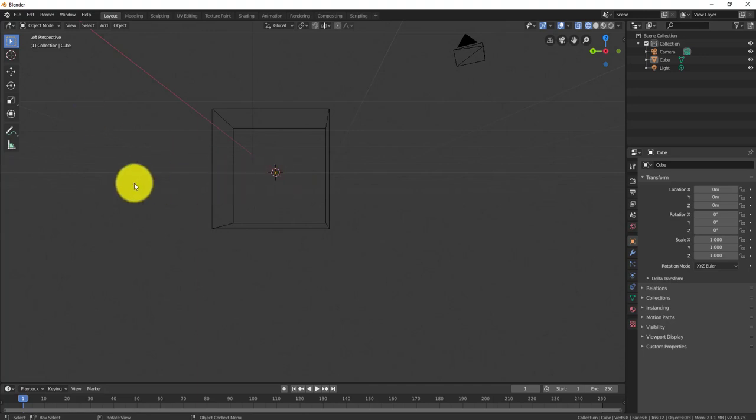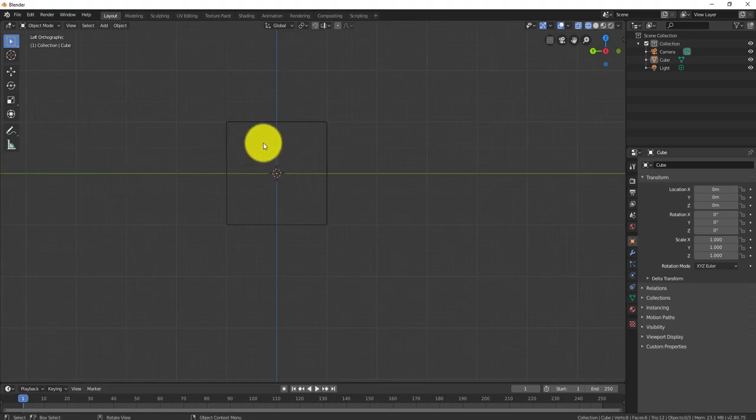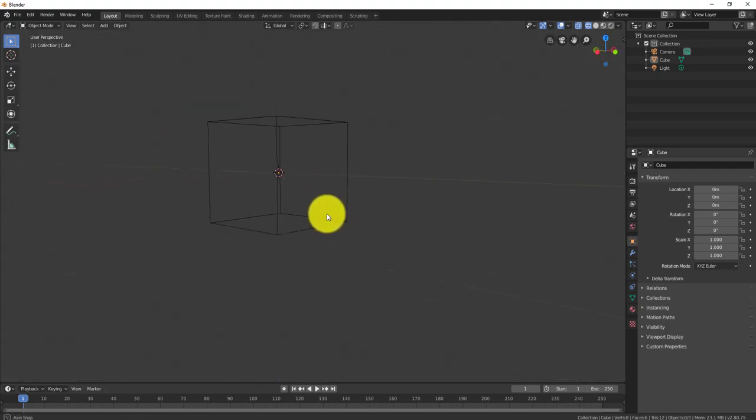If I press 5 again, it shouldn't surprise you that I'm just seeing only a square, even though it's a cube. And the reason why you're only seeing a square here is because you're in the orthographic view. Orthographic view means that all the measurements are real measurements, so even if something's further away, it appears the same size as something that's closer. So this cube is the same on the front and the back. You'll even see if I happen to rotate my screen here, still a cube. But from the orthographic view, I'm in perspective again, but if I go to the orthographic view, there we go, you're not seeing the back side of it. Okay, so there's some views. You can play around with those, and there's some other manipulators.